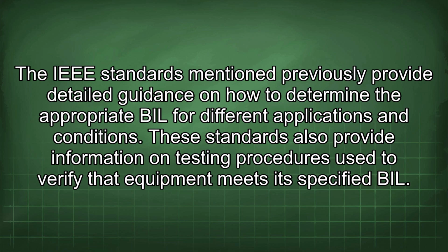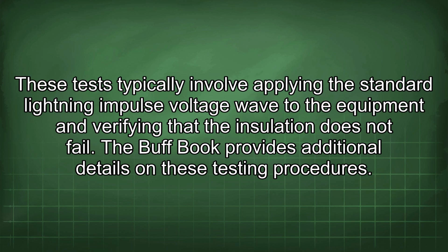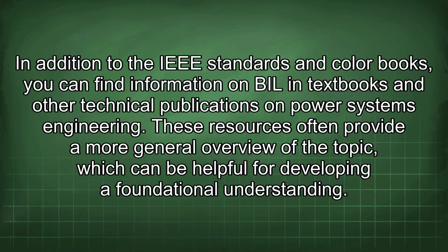These standards also provide information on testing procedures used to verify that the equipment meets its specified BIL. These tests typically involve applying the standard lightning impulse voltage wave to the equipment and verifying that the insulation does not fail. The above book provides additional details on these testing procedures. In addition to the IEEE standards and color books, you can find information on BIL in textbooks and other technical publications on power systems engineering. These resources often provide a more general overview of the topic, which can be helpful for developing a foundational understanding.